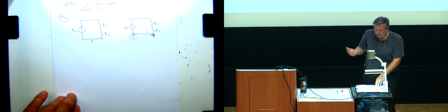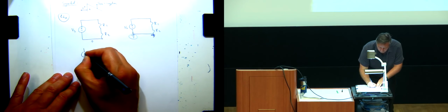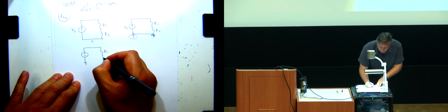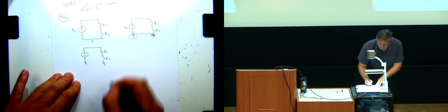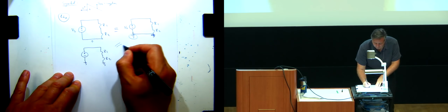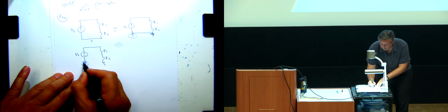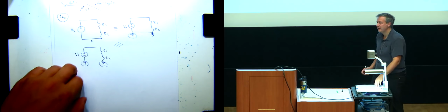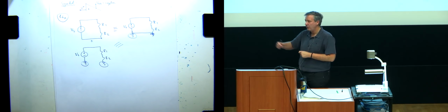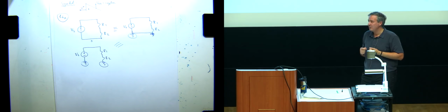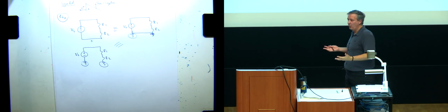Because that's the same node, I will now freely go, just for the sake of removing clutter in my schematics, I will also draw it like this. So all of these are equivalent. This symbol just means anywhere I draw it, it's the same node. There is actually a wire connecting all this. In fact, in your own circuit, that wire will be called ground. Right? If you don't connect all of these points in your actual circuit, it's not going to work.